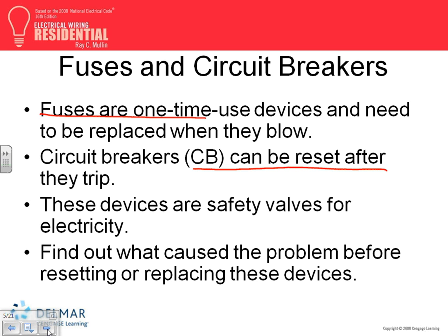If you have a short circuit right at this terminal, and the short circuit is 20,000 amps, and this equipment is rated only for 10,000, what are you going to do? If the short circuit calculated right at this terminal is 20,000, and I bought a transformer that's rated for 10, two things could happen. If you hook up this transformer and have a short circuit, this transformer will blow up, completely burn.